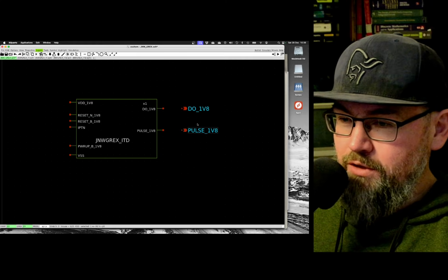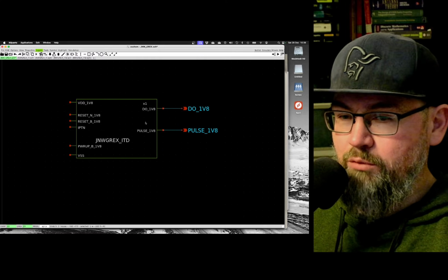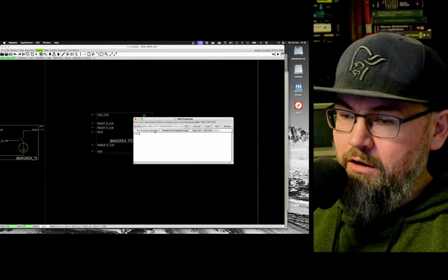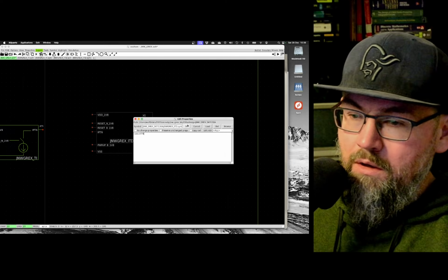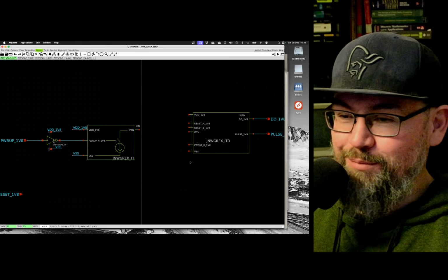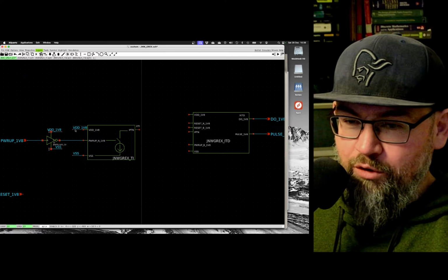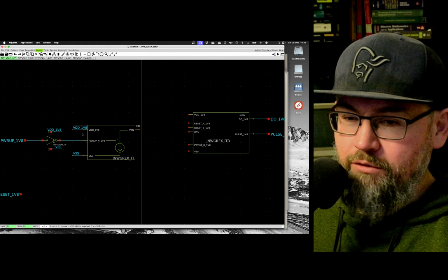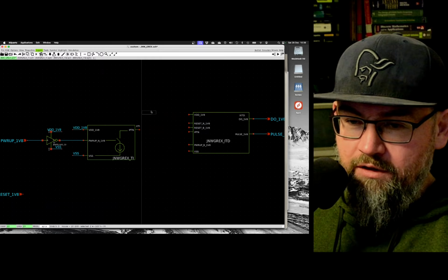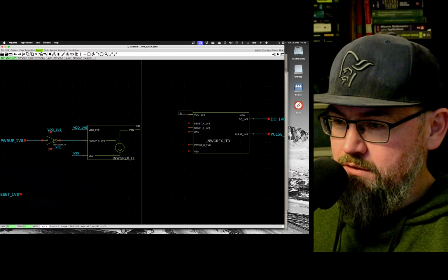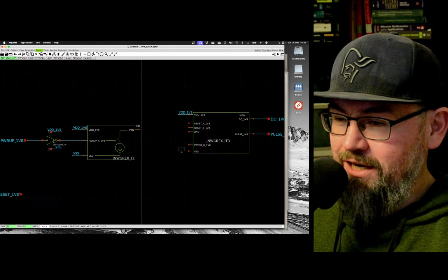That is to make sure that when I do dual rail designs, like 3 volt and 1.8 volts, I try to make sure that I don't hook up my 3 volt supply to 1.8 volt logic gates. That's a very bad idea. And I promise you, that happens.